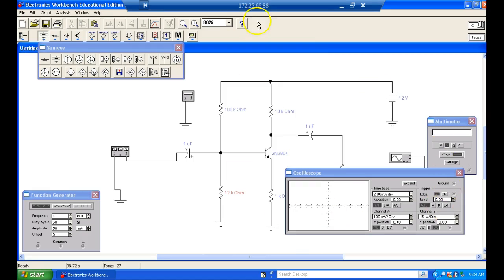It's still got a circuit up through this guy. This guy's seeing it's times beta, so we still have a circuit. This guy's going to drop some voltage, but this guy's going to be 100K and 100K. That means this guy right here should go up to pretty close to 6 volts, which means the transistor's going to saturate. It's going to turn wide open, right? You understand? As wide open as it possibly can. Yeah, it's going to go way up.